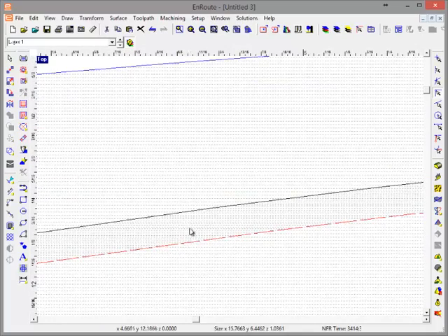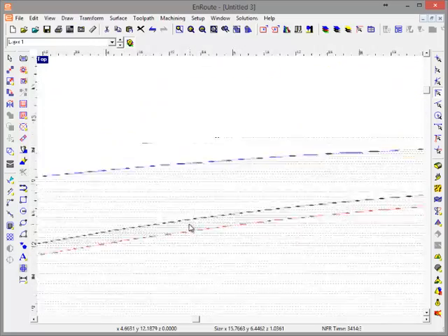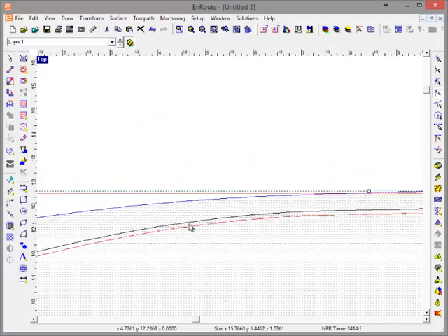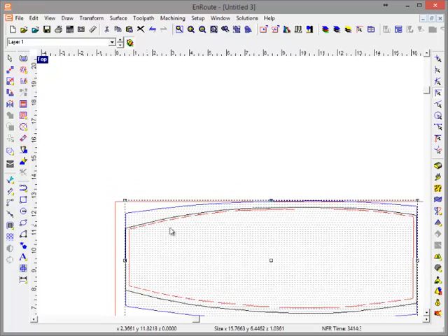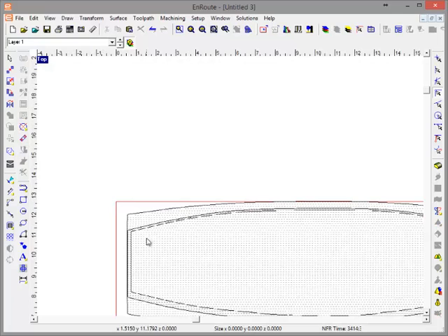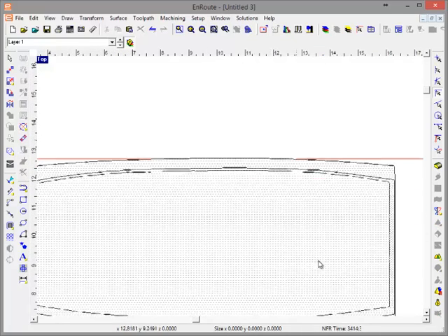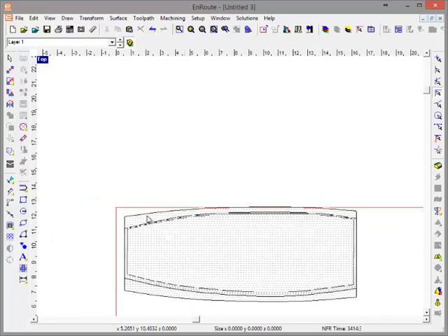As it is, my overlap area is pretty small, which will make it lighter, but possibly not as strong. So when it comes time to do that inline, you might want to give it a little extra thickness there. That is the same thickness as the relief, and that way you would have a little bit more of a shelf there for it to rest on. But as is, it would still work, and it would be pretty light and hollow.